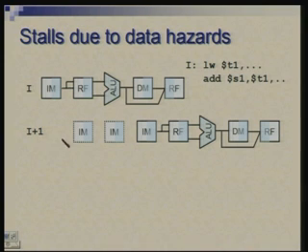So, here I show how you need to stall or delay an instruction because of this hazard. This instruction which would have normally started here in this cycle needs to start a little late, so that register reading takes place after writing has taken place. Now, I have done something a little cleverly here, that actually I am doing this reading not after this cycle, but in the same cycle. This is possible if you can do reading in the later half of the cycle and writing in the earlier half of the cycle.